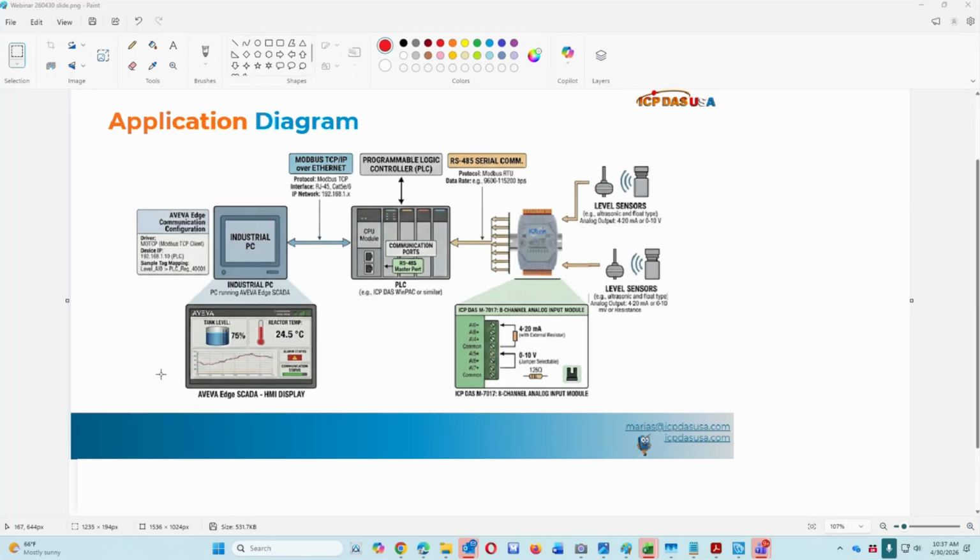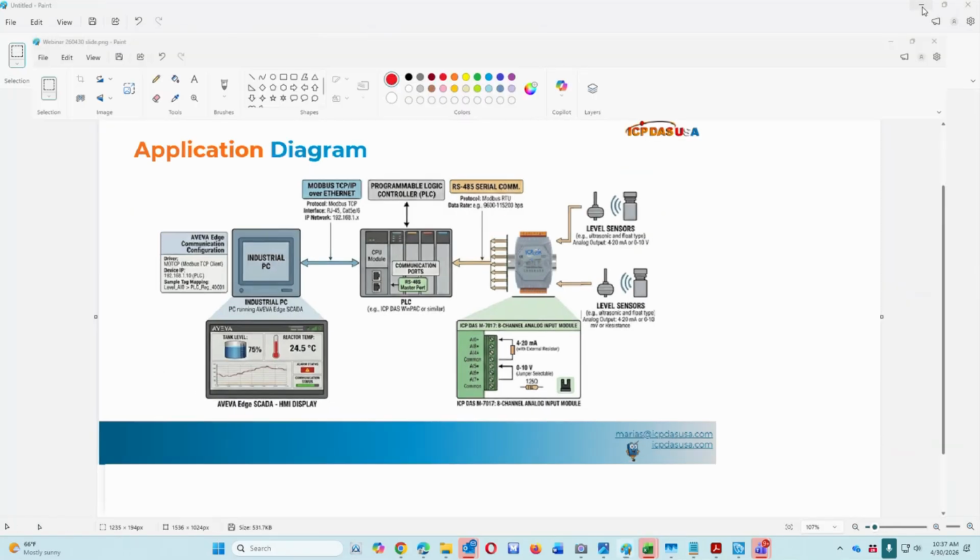But Modbus TCP allows you to communicate locally through an existing Ethernet network or a private network. It allows you to do port forwarding through the internet to share data to other facilities, to other areas, and you can also communicate to cellular modules using Modbus TCP as well through proper networking. Let's see, let me go to the next presentation.